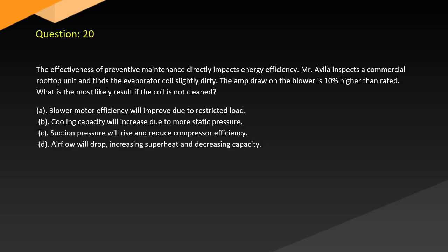A. Blower motor efficiency will improve due to restricted load. B. Cooling capacity will increase due to more static pressure. C. Suction pressure will rise and reduce compressor efficiency. D. Airflow will drop, increasing superheat and decreasing capacity.